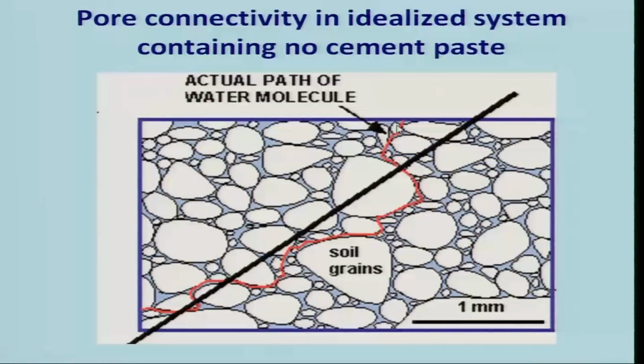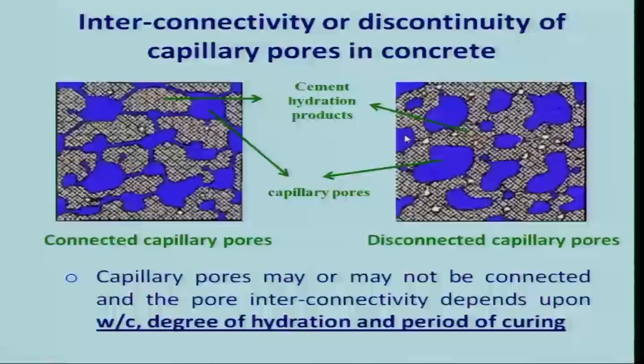So we prefer a discontinuous system so that water or external agents do not permeate through the Portland cement based paste system, so that no chemical reactions or other things happen inside. The goal is primarily to achieve a discontinuous system, so that the Portland cement based system may have porosity, but the permeability is substantially lower.